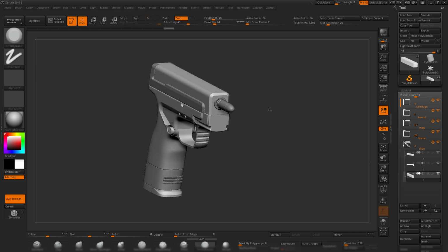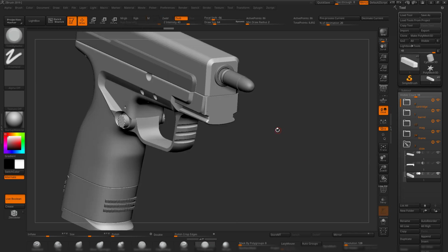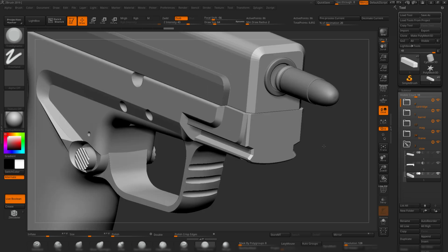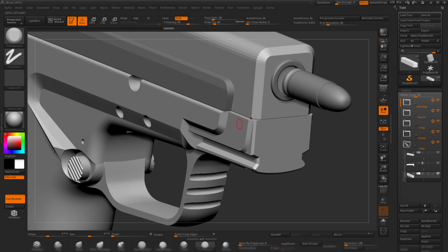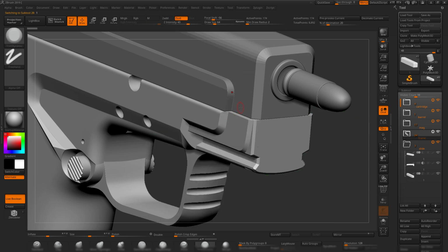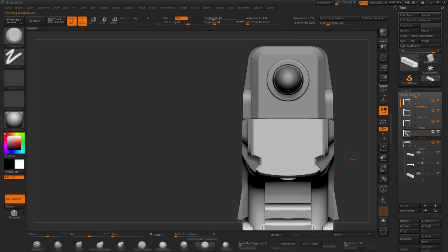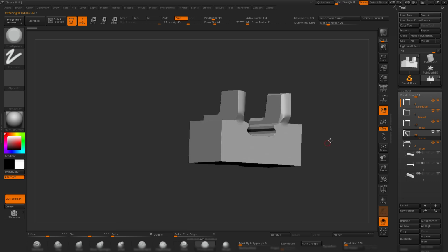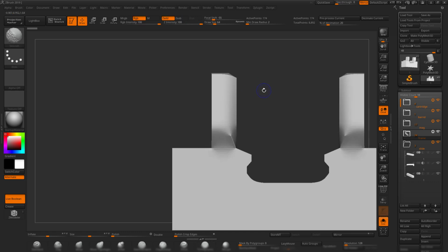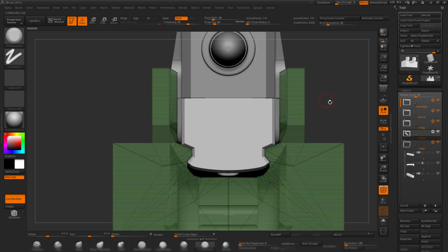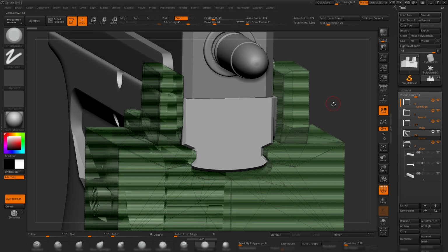It's looking much better. Another issue that appeared is this surface on the frame, which is not corresponding to this one, and this is pretty easy to edit as well. Just go into this shape, Shift D, and select the surface that you want to move.